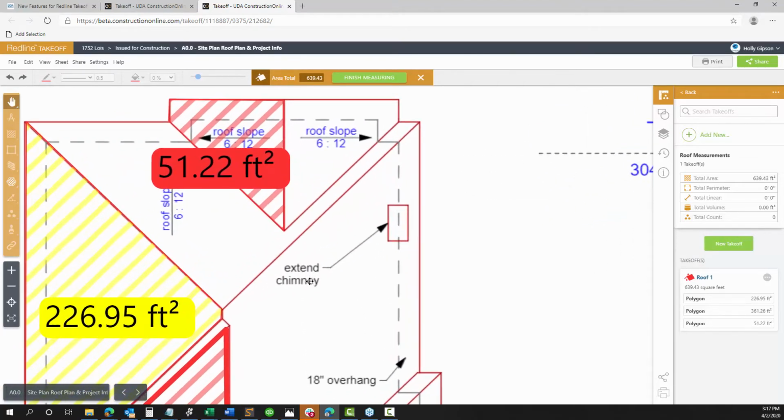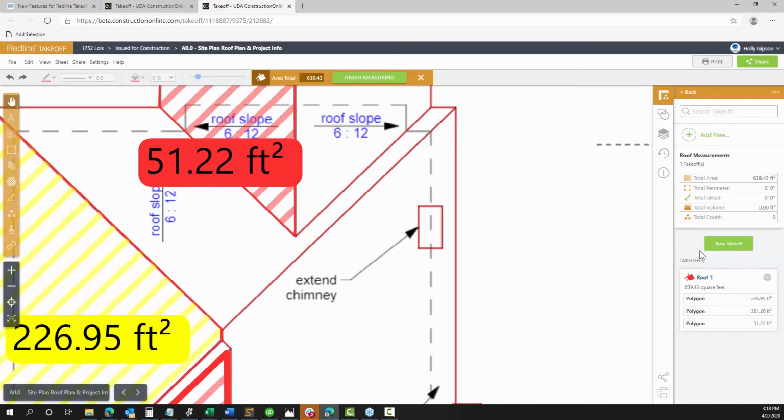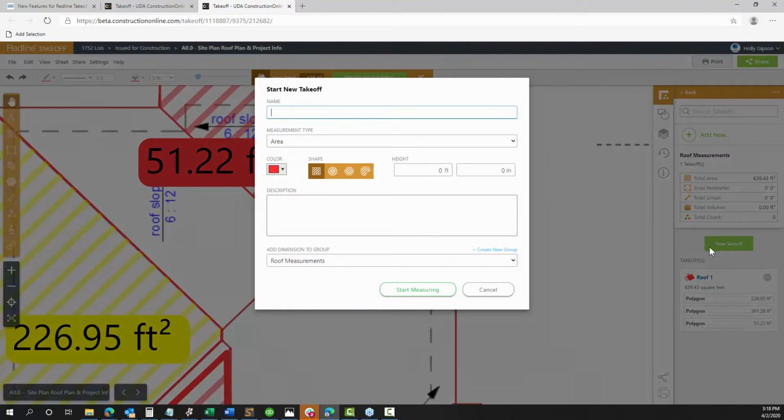But sometimes if you are measuring out perhaps framing or other roof materials, we may want to do just a linear measurement, say maybe of this ridge or a valley. You can do the same thing that we're doing here with the area tool by using the pitched linear tool. So that'll just help us take those straight line measurements, add a pitch there, and then be able to get a more accurate measurement that way.